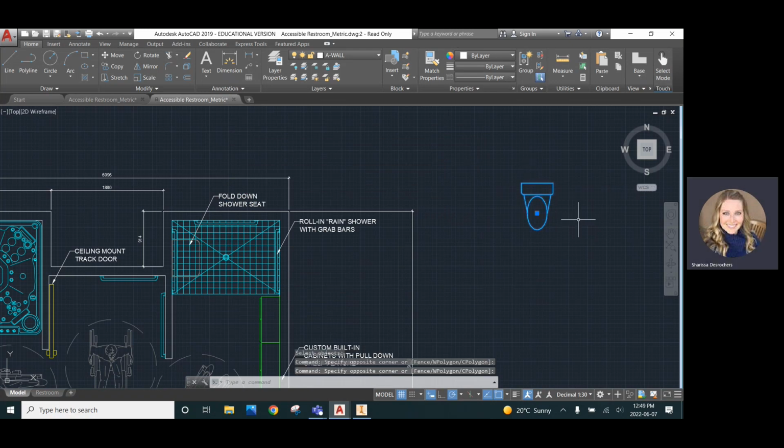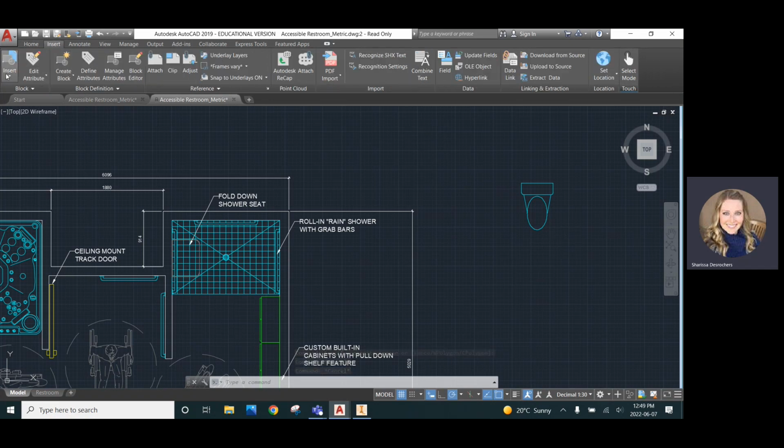And then you're like, okay, well, why is this beneficial? It's beneficial because now it's saved to a block library and you can insert blocks. If you go to insert and drop down the insert, it's going to have a library of everything that you blocked. So you can make a library of walls. You could make a library of handles, like the wheelchair handles or assistance bars. You can make a library of tubs, whatever.